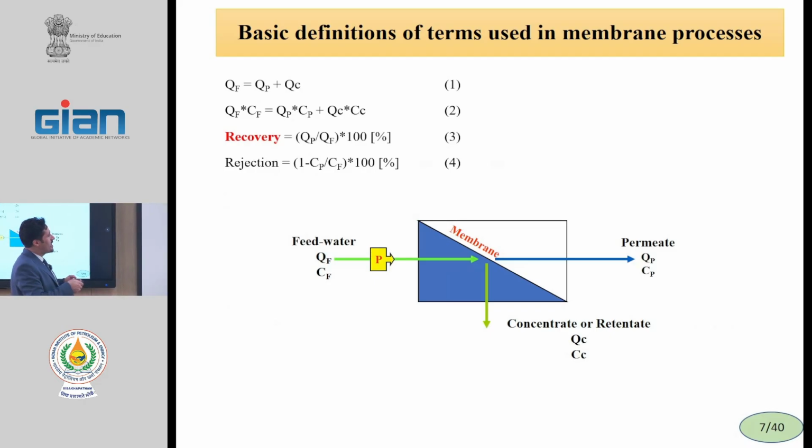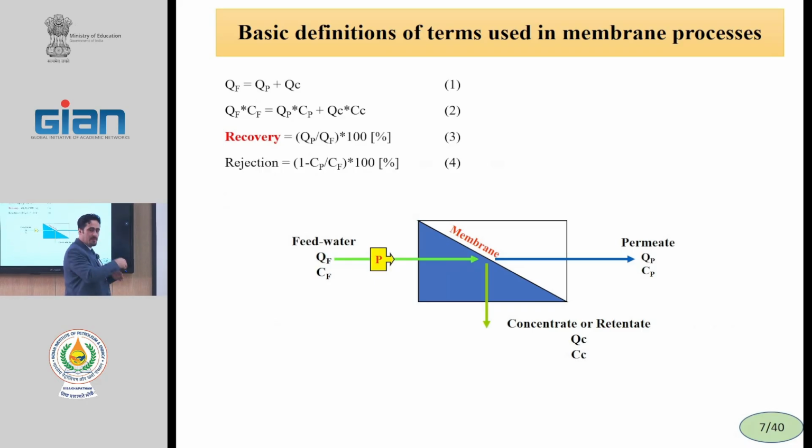And when we have a high concentration of solutes on the membrane surface, it causes high fouling. We can separate all of the solvents from the liquid, but when we separate all of the solvents, a layer will cover the membrane surface and block all the surface, and the membrane will be destroyed.